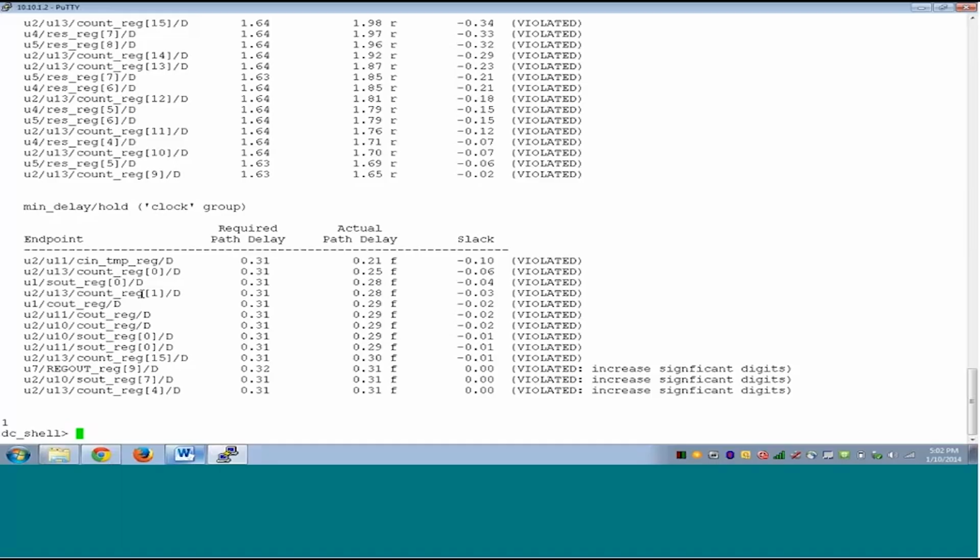Either in this way, or the things will change when multiple clocks come into account, right? So the best practice is to register all inputs and outputs so that the timing constraints become very easy. Second, if you realize that your register to register timing is violating and you expect the timing to pass, look at the other groups. What the other groups are violating. Make sure that you segregate groups. Things become much more complex when you have multiple clocks. Then you have to make sure that the inputs get input delay with respect to the correct clock, not the wrong clock.